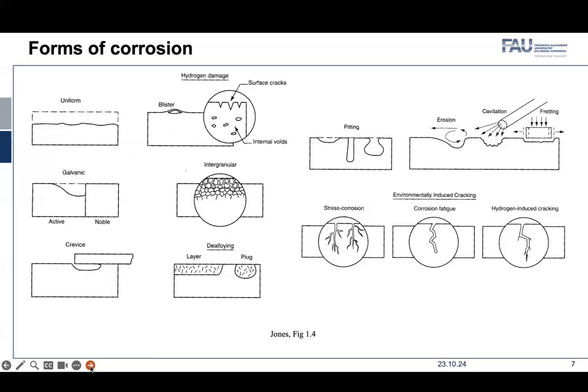So then the passive film forms. In the case of intergranular corrosion, the passive film is absent in the grain boundaries. Without the passive film, they continue to corrode. So you can see the grain boundaries are selectively attacked, and sometimes individual grains in the material may fall off and can create significant damage.